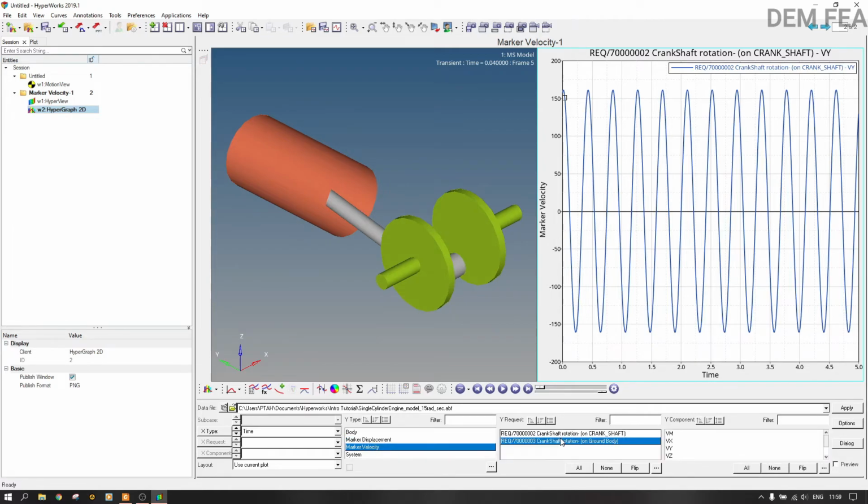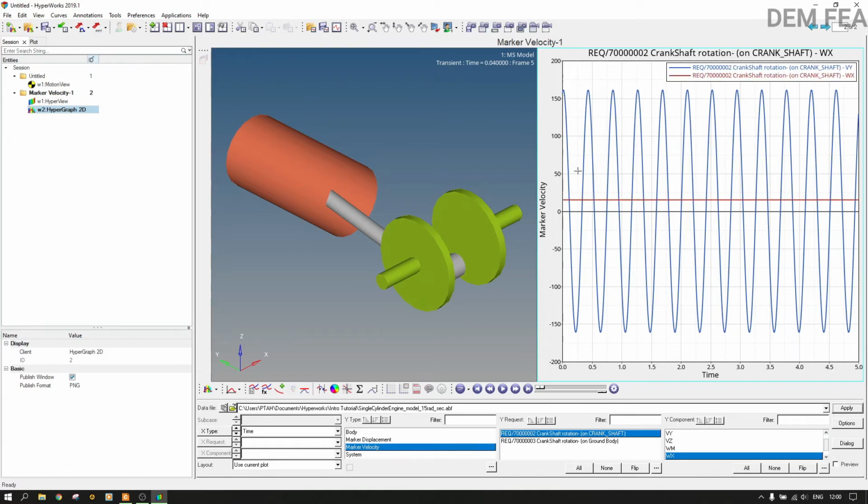No, it's not that one. So we can also do something else. We can add another graph here. So we want to see the omega x. Omega x is the rotation, the 15 rpm that we have put. Now, no, 15 radians per second, not rpm. So we say apply. Now you can see this line, this represents the 15. Now, once you run your simulation like that, you'll see that as it goes, and so on and so forth. Now this is just an overview of this software.